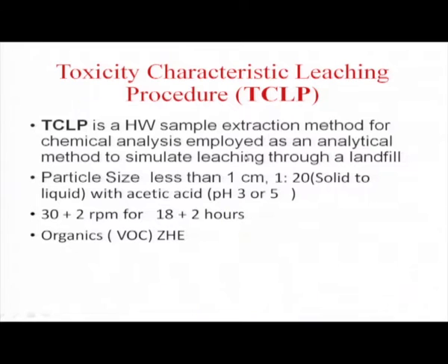And what are the procedures involved in carrying out the test? Because the hazardous waste sometimes may be a slurry, liquid form, or mostly in the solid form. If it is a very high solid but the particle size is greater, the particle size should be reduced first, because as a bulk material it may be available in the actual industry.